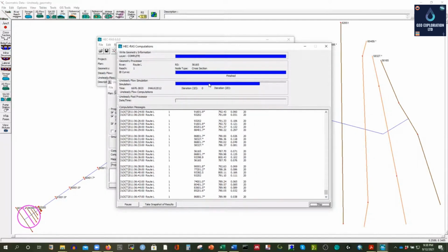But for other cases, maybe it is useful if you have a natural canal or channel and you need to optimize, because these are basically prismatic canals, the regular shape of the canal, right? It is artificially constructed, so we call it a prismatic canal. And if it is non-prismatic, meaning a natural canal, then you need to use even the minimum time step, then your model will be stable. So we have to test this time step.